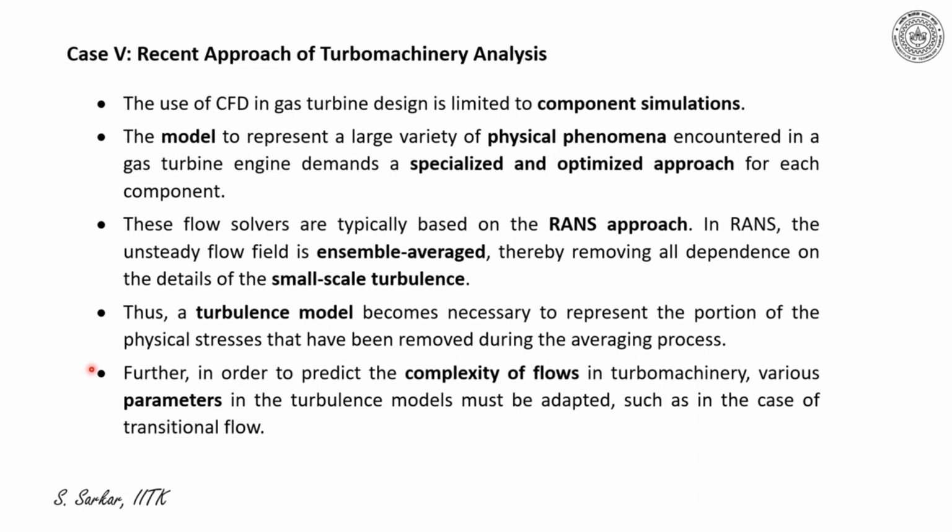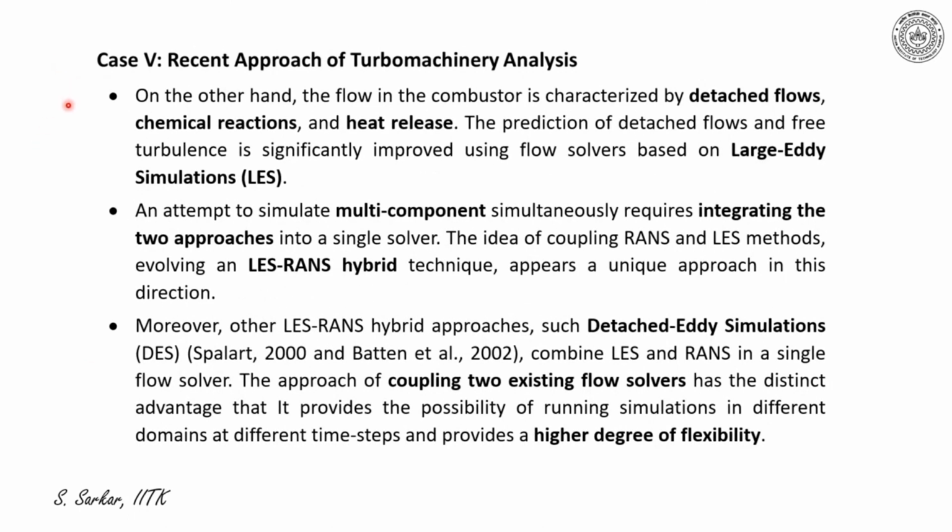that while predicting transitional flow, we incorporate some modification or addition in the turbulence models. On the other hand, the flow in the combustor is characterized by detached flow, chemical reaction, and heat release. The prediction of detached flow and free shear turbulence is significantly improved using a flow solver based on large eddy simulation. An attempt to simulate the multi-component simultaneously required integrating two approaches in a single solver. The idea of coupling RANS and LES methods, evolving an LES-RANS hybrid technique, appears a unique approach in this direction.